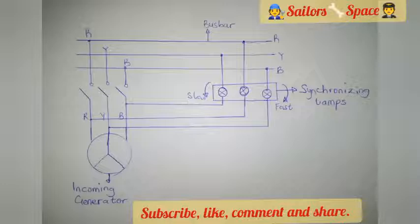If you notice also in the diagram, there's an arrow that shows slow, and an arrow that shows fast. Now the synchronizing lamps are three. The one that's connected to the red phase is called the main lamp, while the ones connected to the yellow and the blue phases are the auxiliary lamps. Now, for you to know that the system is in the correct phase with the incoming generator, the red lamp, which is the main lamp, will be dark, while the other two, yellow and blue phase lamps, will be equally bright.